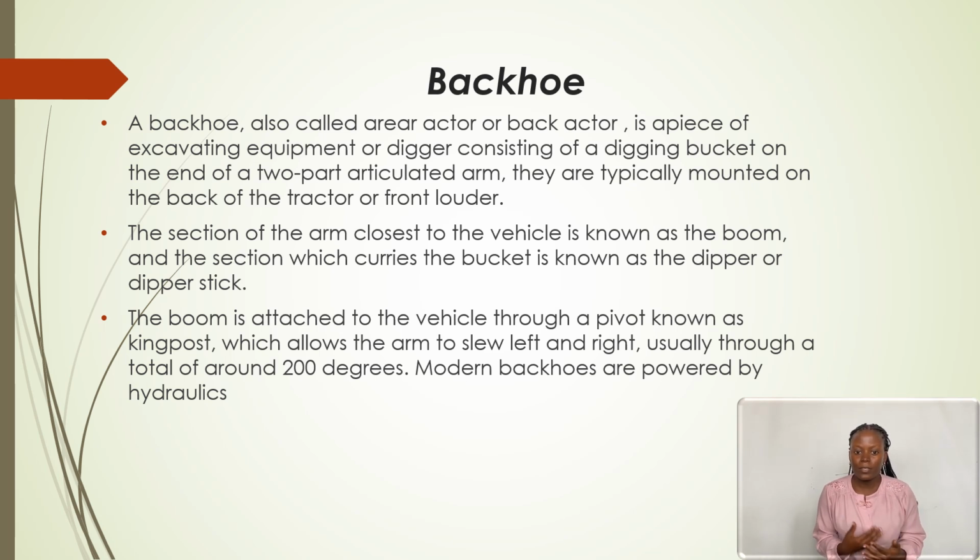The boom is attached to the vehicle through a pivot known as a king post, which allows the arm to slew left and right, usually through a total of around 200 degrees. Modern backhoes are powered by hydraulics.